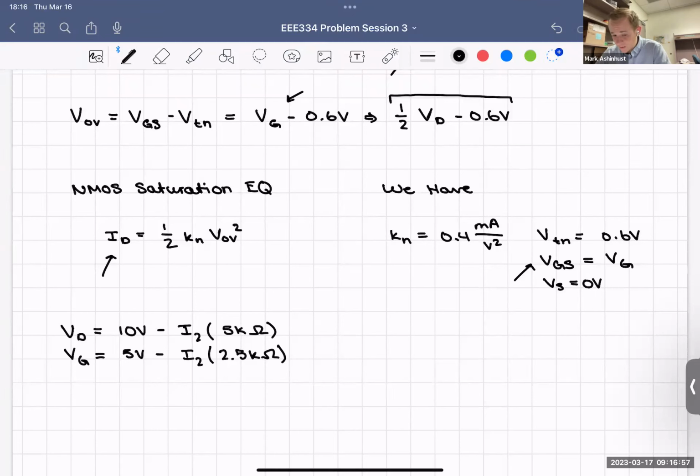So I2 is not the same thing as ID, right? I2 there is split. Kirchhoff's current law: all the currents in that sum to 0. Whatever's entering a junction must leave. So I2 is also I1 plus ID. I1 is what we're going to be seeing coming out past, right?